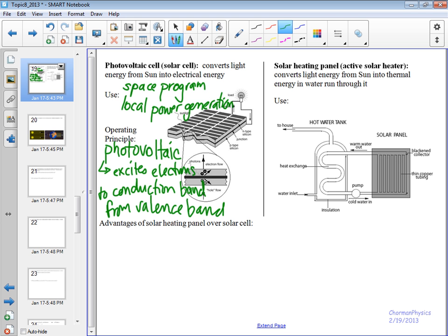The other form of solar energy is going to be solar thermal heating, basically, where we can take a black panel, and put it over some pipes and collect thermal energy that way, absorb the sun's light, and run water through those pipes and be able to heat that water up, okay? Typically, this is used for hot water, all right, in domestic uses, all right? We also see solar thermal. We see these parabolic troughs. We'll talk about them in a little bit, but they're basically these parabolic mirrors that help to heat steam up and run a power plant that way.